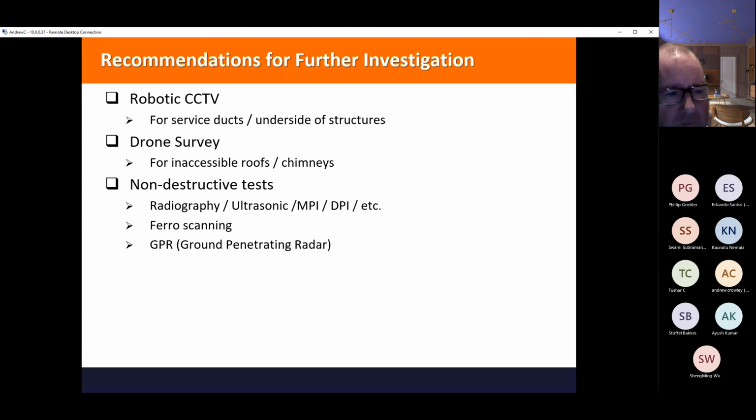Now, they come in a variety of packs, from a very basic beep to a very much more advanced and much more costly full scan, which gives you the depth and size of the reinforcement in your wall or floor. The more advanced ferroscanning is available as a specialist service.